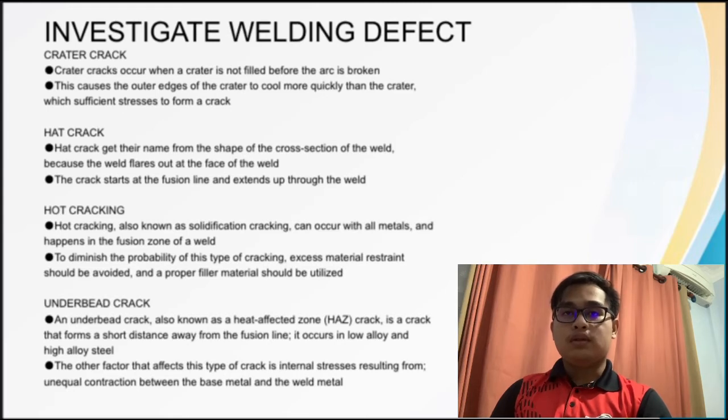Hot cracking. Hot cracking, also known as solidification cracking, can occur with all metals and happens in the fusion zones of a weld. To diminish the probability of this type of cracking, excess material restraint should be avoided and a proper filler material should be utilized.